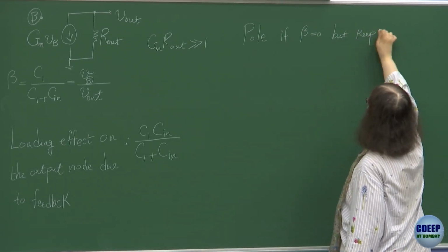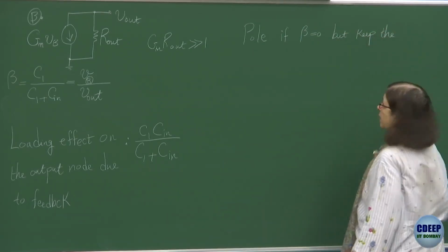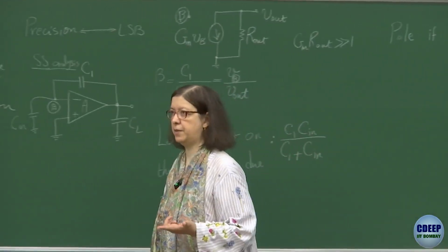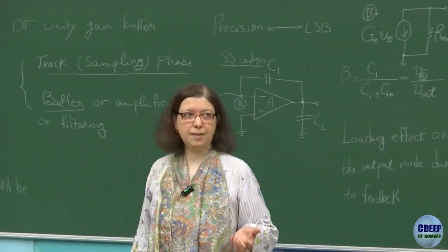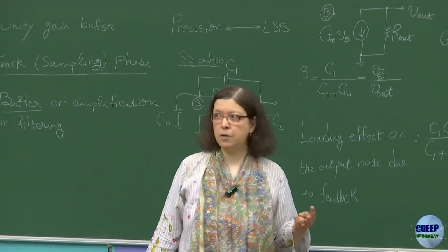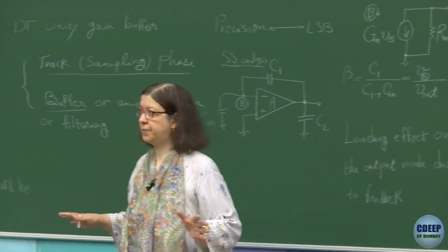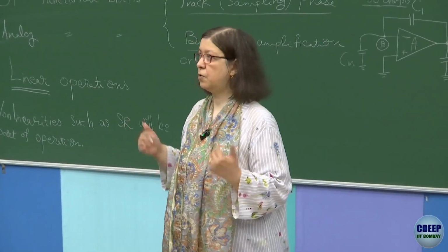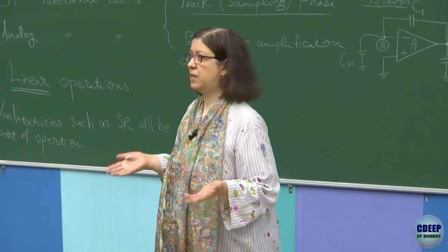This is very important. I don't know if you have a background in feedback system analysis, in linear feedback theory. When you want to analyze a feedback system, you need to first consider the loading effects. Loading effects are independent of the feedback factor. That means even if the feedback factor is 0, loading effects remain. It's not an ideal feedback.